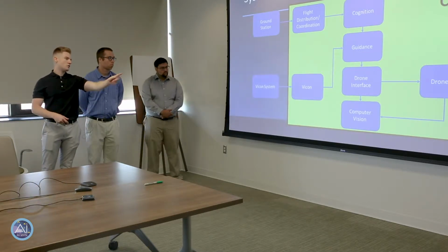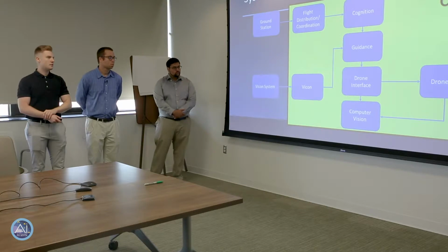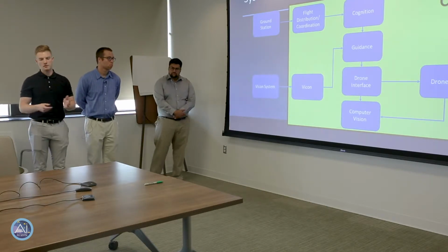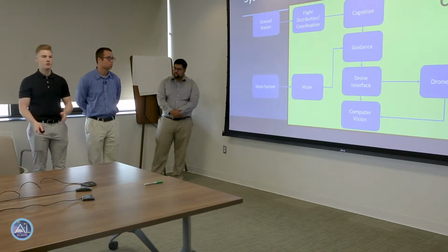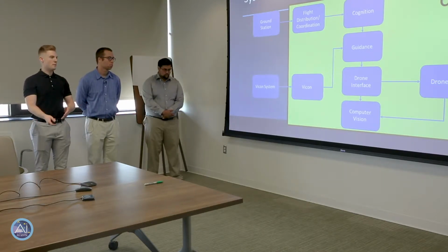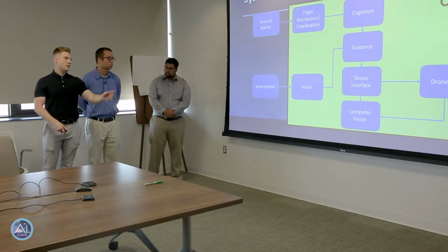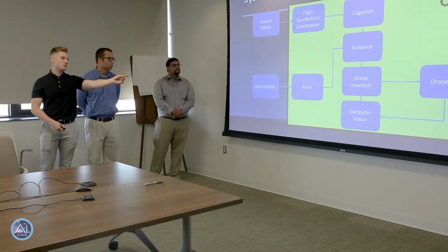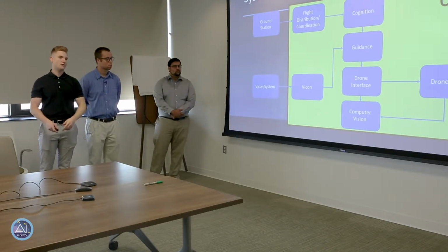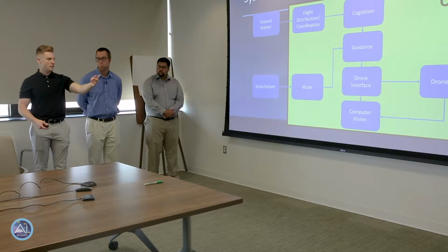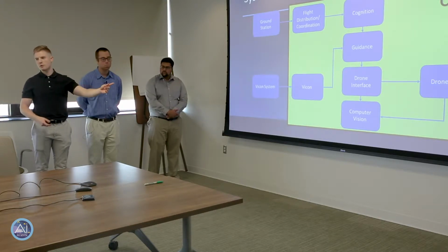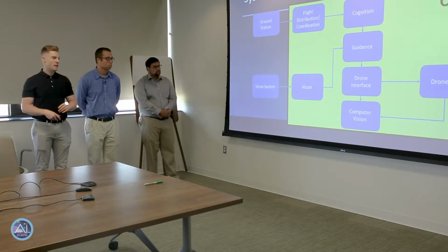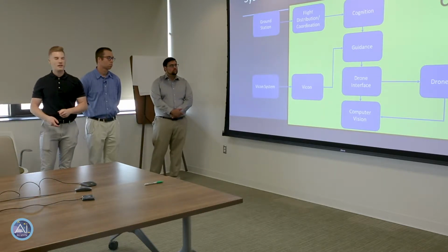In our case, the drone API we actually don't have in CFS, because it's Python based, and ICAROUS cannot use the Python based structure. But there is a C base that could be ported for that. And what happens is we have the drone interface send the information to the API where it actually physically controls the drone, and then the camera will pipe back into CFS where computer vision is entirely wrapped into the structure itself. And then we're able to detect damage and such that way.